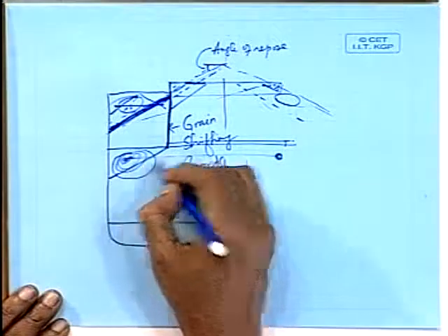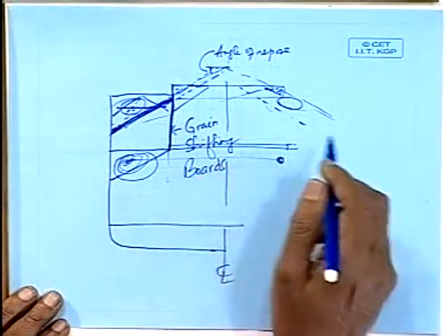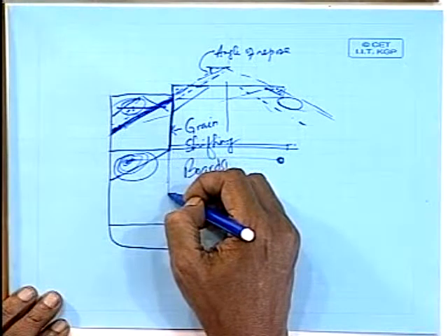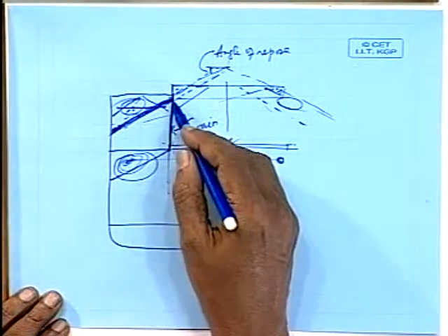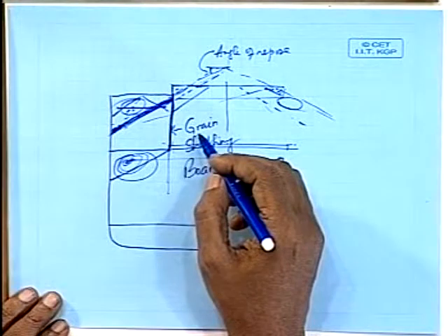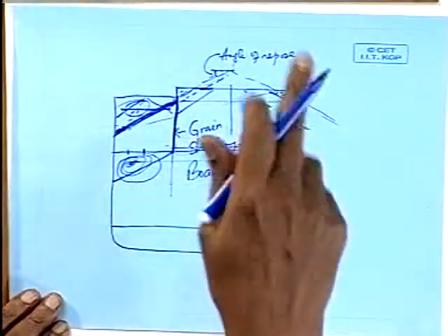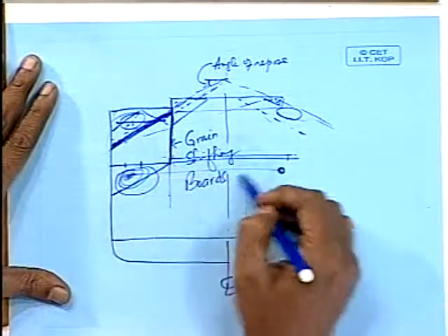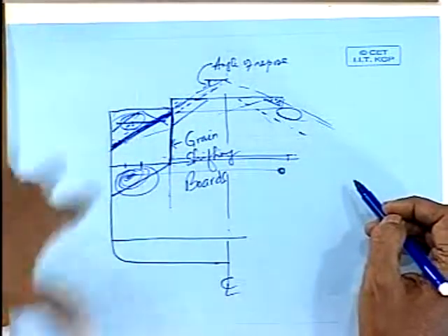What about this portion? Sorry? It can come down. That is down here like this. Then what goes here? So we can have some pull type of arrangement so that the grain can be put out from there. Right. An easier option will be if I can have access here. I cut large openings with gratings and temporary covers so that when I am carrying general cargo, that can be closed. You know, not watertight. My watertight envelope is this. I don't require any watertightness here. So I could have some cut with grating.